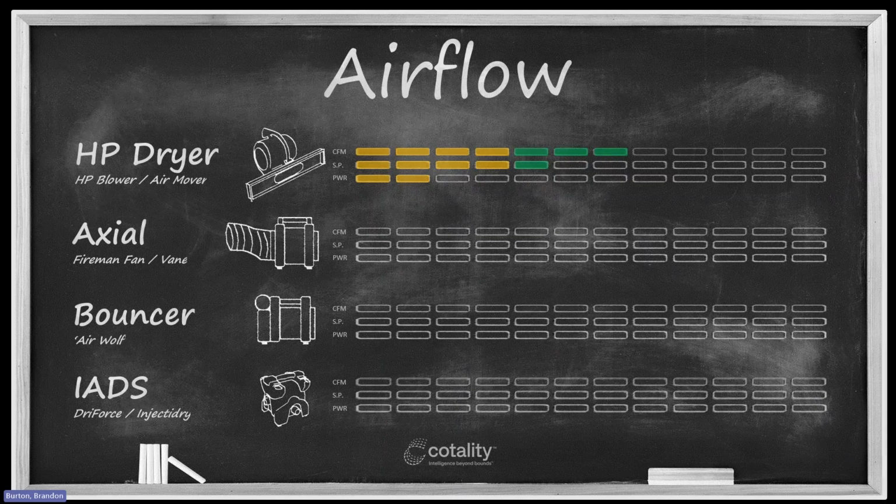All right. The power efficiency is not great, though, because it's got really good CFM and decent static pressure. The trade-off for that is they draw a lot of power. Usually an HP carpet dryer is going to be around 9, 10, 11 amps. That means that it's pretty much going to consume an entire 15 amp circuit all by itself. Right. And sometimes that 15 amp circuit is all I've got for 3 or 4 rooms. Right. So one of these on that circuit is going to pretty much tag that circuit out from me being able to run much else for drying equipment. And again, that's a big red flag for me. I would still use these in certain circumstances, and I'll show you where here in a little bit. But generally speaking, I do not like the energy efficiency.